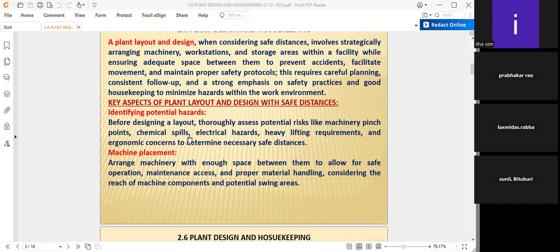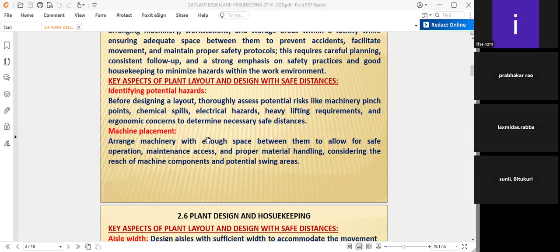Like this, if the main stores department is far away from the process department, we cannot avoid it during orientation. Therefore, we have to plan some service store in the process department, so that the spillage of the chemicals will not occur. Why? Because some carboys are there, which we first store in the departmental process service storage, and after filling up the departmental process storage, then go to the main storage. Then to avoid the chemical spills also.